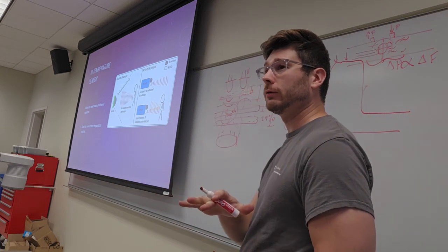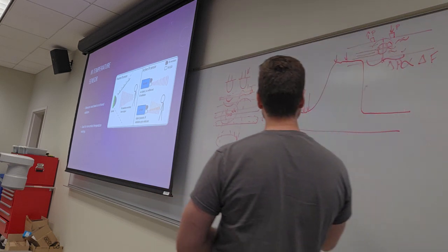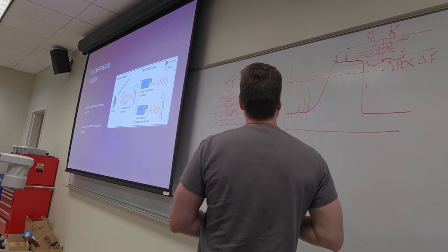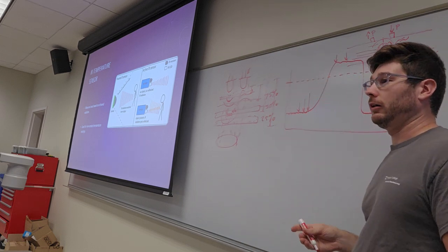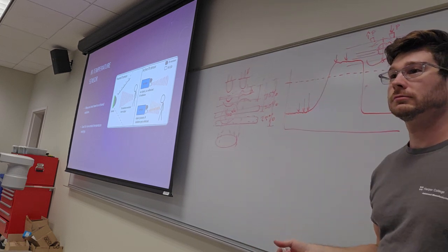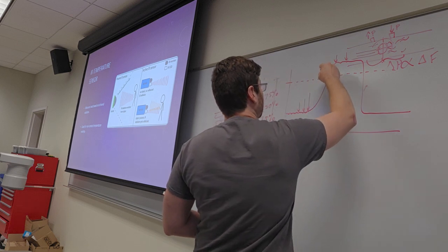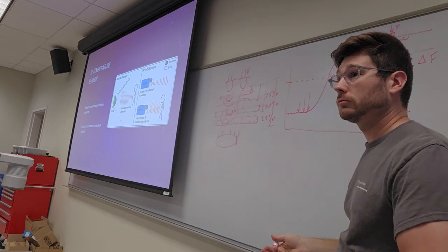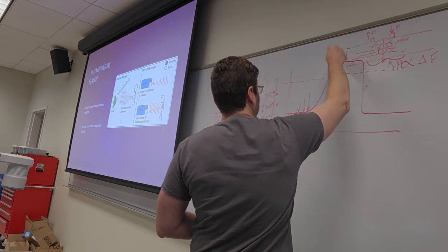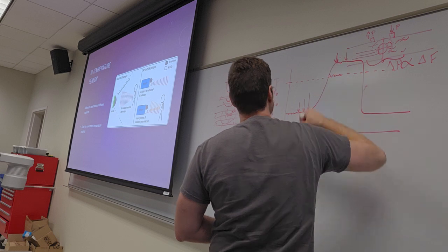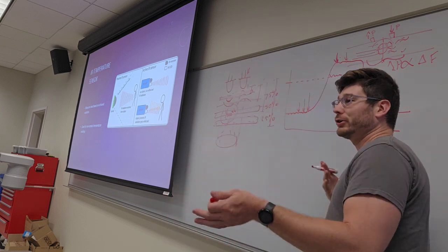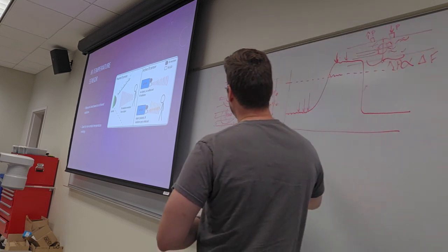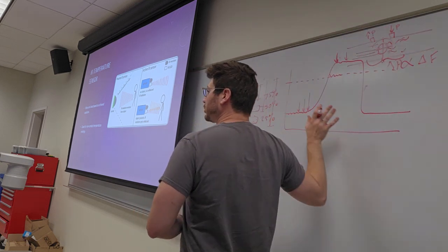There's a couple techniques that we've already talked about that you could use. The simplest one is a simple threshold: if IR val over threshold val, turn on the faucet, right? But we've talked about ways that this can go wrong. If you have noisy data, you might want to add hysteresis. You might want to do a peak detector or something. You could do set-reset logic, so you don't trigger the thing all the time. This is kind of where transducers end and logic begins.